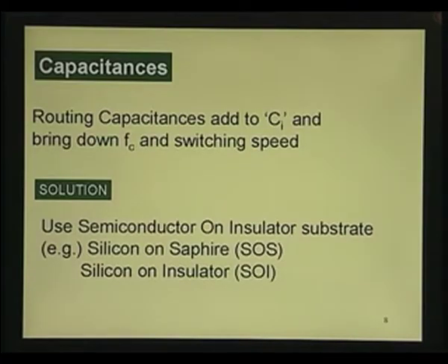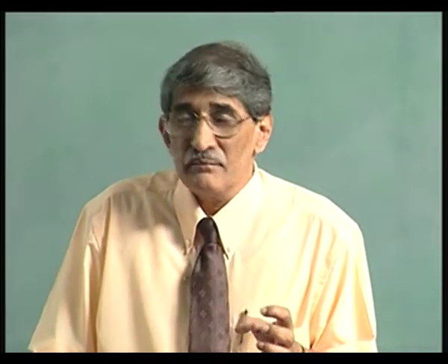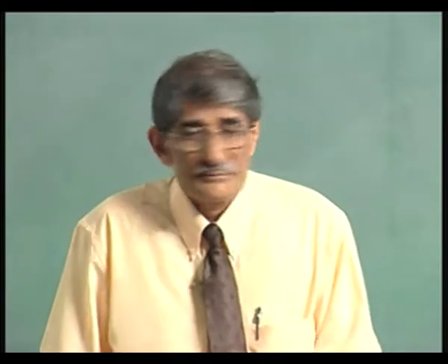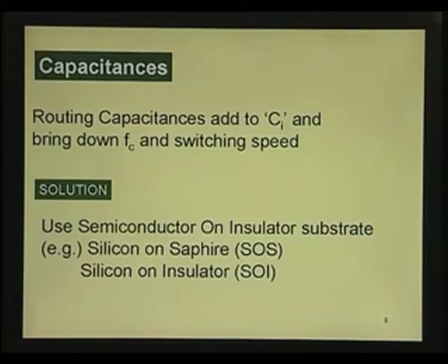The other thing that we will have to be concerned with is that the mobility is not so much dependent on frequency, okay, because in the frequencies that we talk of, they do not vary. They are dependent on field, okay, and temperature. If you go to very high fields, they will be changing. Otherwise, with field it does not change. Okay, I am sorry, with frequency it does not change. That is a constant. In fact, even at high frequency they use that concept. Okay, constant mobility. Because all those equations that one develops are based on constant mobility with frequency.